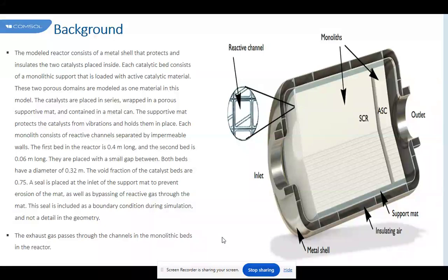This asymmetry may come from the fact that the fluid approaches the substrate mainly to the center of the converter. However, there was still a marked preference of the fluid for passing through the monolith that imposes the lowest viscous resistance despite its location. Regarding back pressure, this simulation shows its sensitivity to the size of the core.